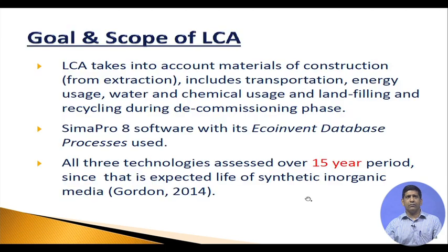In terms of life cycle, it started from the goal and scope. The LCA will take into account construction, transportation, energy usage, water and chemical usage, landfilling, recycling, whatever we need for the decommissioning phase. We used the SimaPro 8 software. You don't have to use this software, but it is very commonly used, along with the ecoinvent database. One thing I would like to let you know: as a non-OECD country, in India, if you are working on an LCA exercise, the ecoinvent database is available to us for free in an academic setting. So you should be able to get the ecoinvent database.